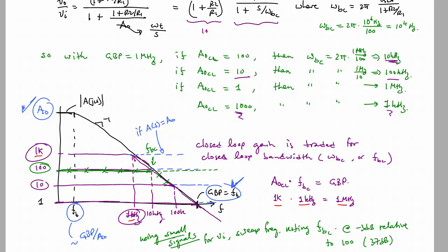I would take data up beyond that, get enough data points that when you plot this, you see there's a nice break frequency and then a straight line that's descending 1 decade in amplitude per decade in frequency. And then you can stop. You could extend this and keep taking data until you actually had a closed loop gain of 1, like out here. And that would be your gain bandwidth product frequency, FT.